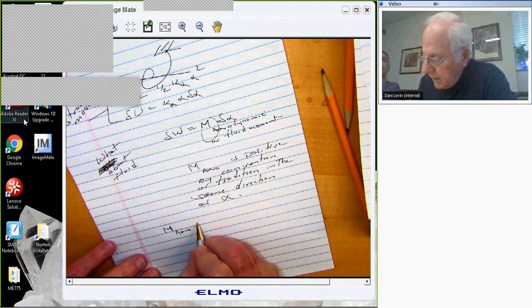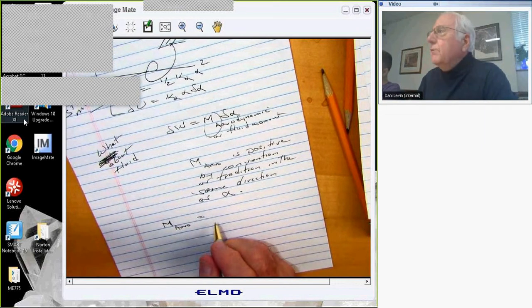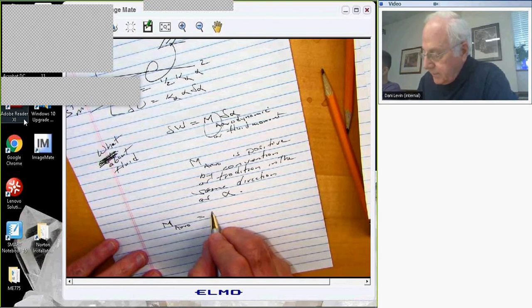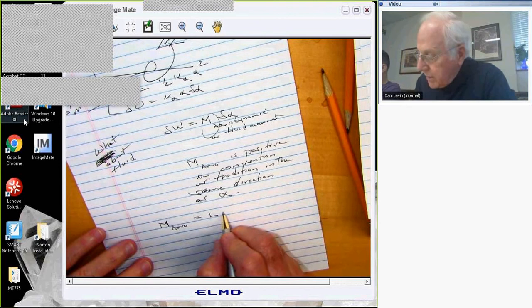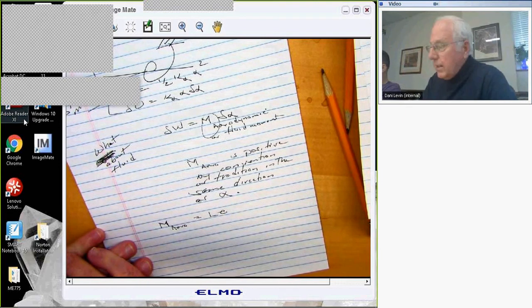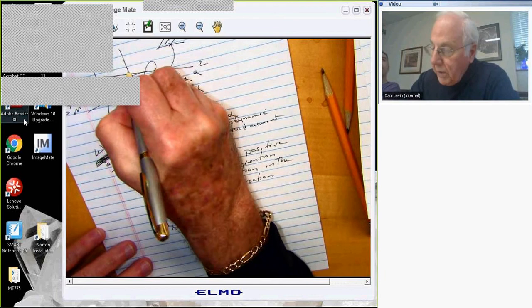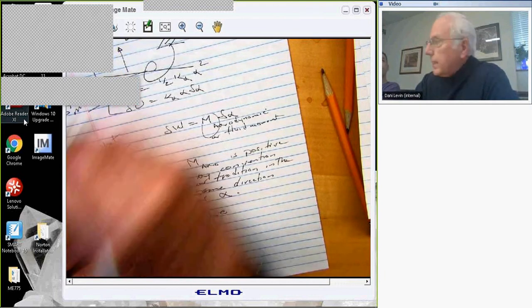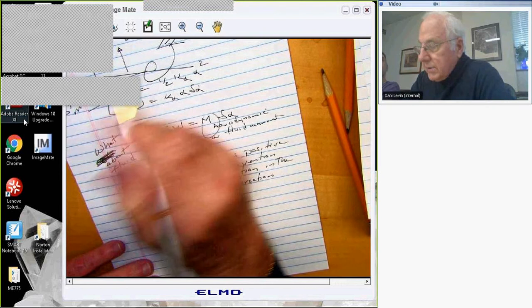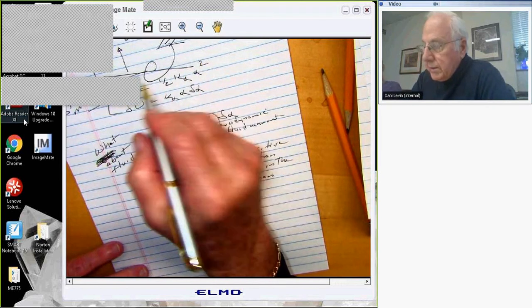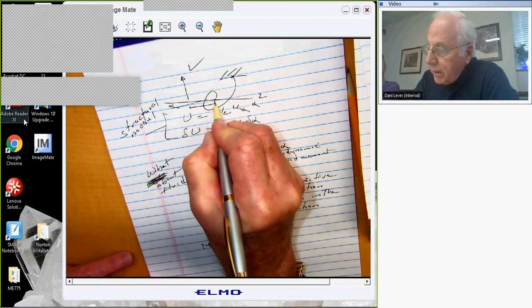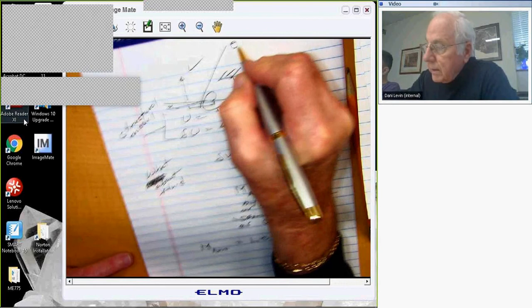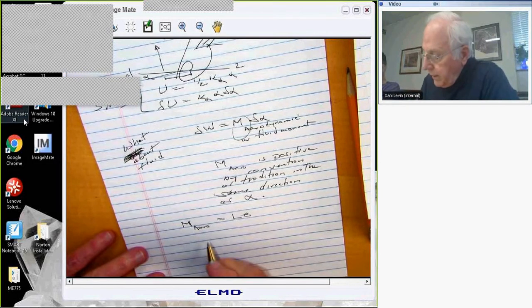First of all, it's the lift, which is the vertical force acting on my airfoil, times the distance, E, which is the distance from where the lift acts. It's, if you will, the center of pressure. So it's the distance from here to here. And the lift itself, my aerodynamicist friends tell me, is proportional to alpha.